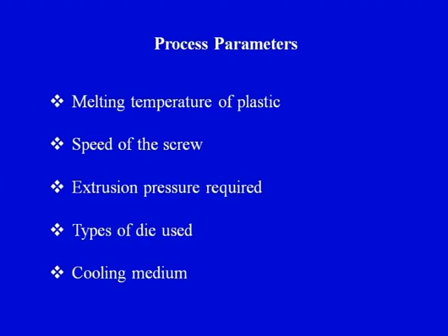Now the contaminants can be arrested, the cooling can be done, and there can be other attachments which may further improve the efficiency of the process. But the basic process is that we would be melting the plastic inside the barrel and then pushing that molten plastic through the die opening to get the final product. So we will see some of the other important details related to the extrusion process.